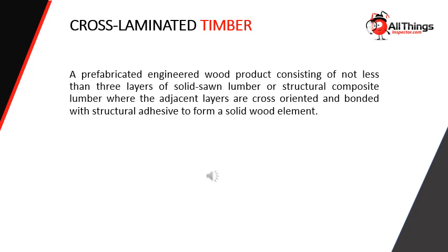Cross-laminated timber, a prefabricated engineered wood product consisting of not less than 3 layers of solid sawn lumber, or structural composite lumber where the adjacent layers are cross-oriented and bonded with structural adhesive to form a solid wood element.